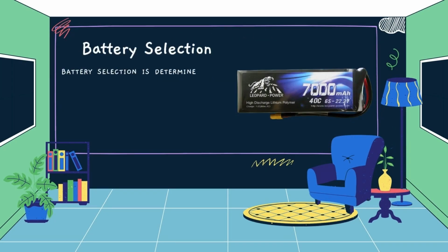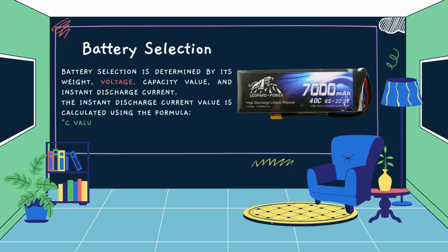We have decided on the type of unmanned aerial vehicle we will design. Accordingly, we have learned our weight. We chose our motor suitable for our agility requirement. We determined the ESC and which inch propeller to use according to the motor. Now it's time to choose the battery.